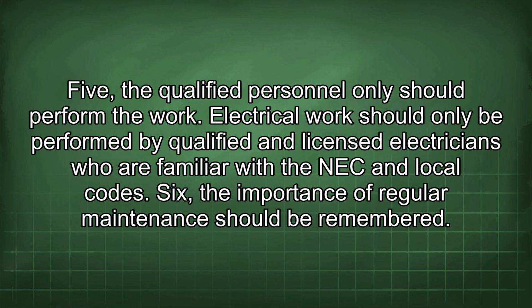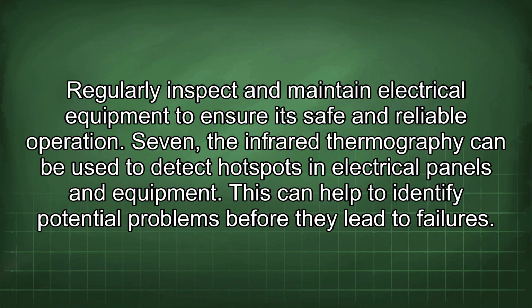5. Only qualified personnel should perform the work. The electrical work should only be performed by qualified and licensed electricians who are familiar with the NEC and local codes. 6. The importance of regular maintenance should be remembered. Regularly inspect and maintain electrical equipment to ensure its safe and reliable operation. 7. Infrared thermography can be used to detect hotspots in electrical panels and equipment. This can help to identify potential problems before they lead to failures.